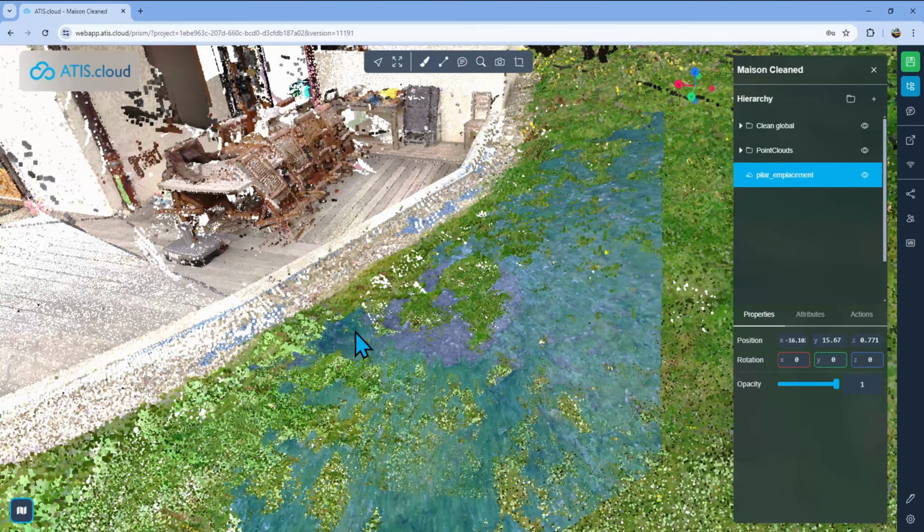We'll use that to buy the support for the panels, because obviously these don't just stick on the roof. You'll have to put 2 racks per line of panel to have them basically hold on the roof. You attach the rack on the roof, and then you attach the panels on the racks so that they can actually hold. So basically you'll have 2 racks for the upper line here, and then 2 racks for the line that is just below, and then 2 racks for these two, and then 2 racks for these ones.